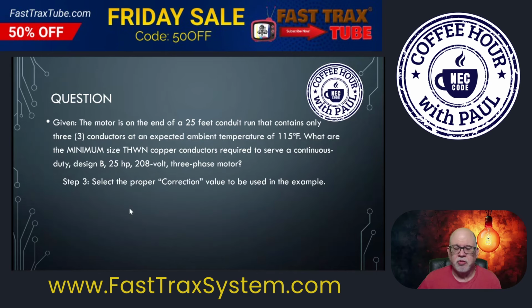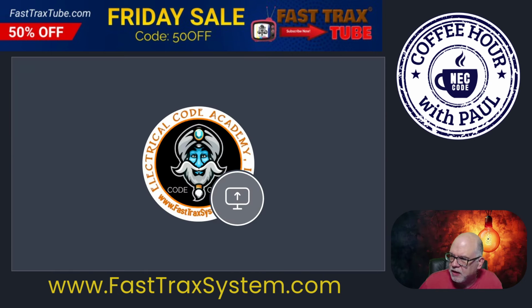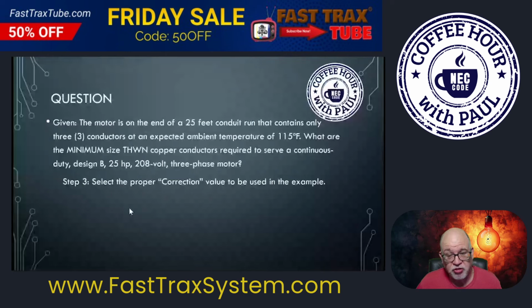All right. So now we've got all that. We're putting all the pieces together. The next thing is, okay, let's deal with this ambient correction, right? So we're dealing with 115 degrees Fahrenheit. So we have to select the proper correction value to be used in our example, because yes, we do have to take the ambient into account. You can't just discount it and disregard it.